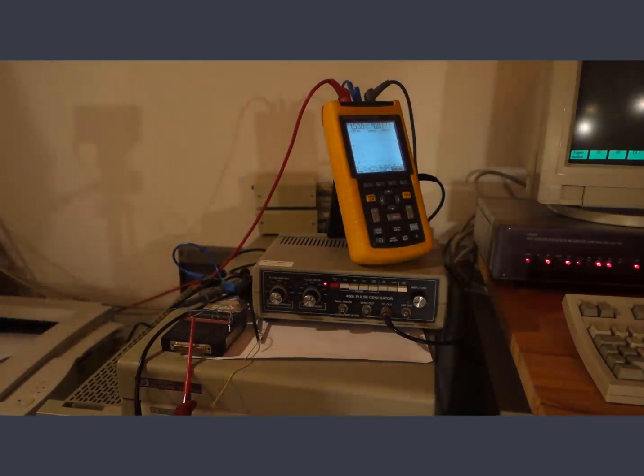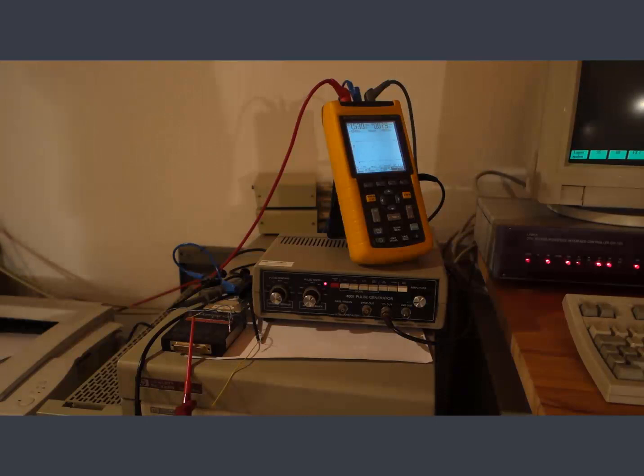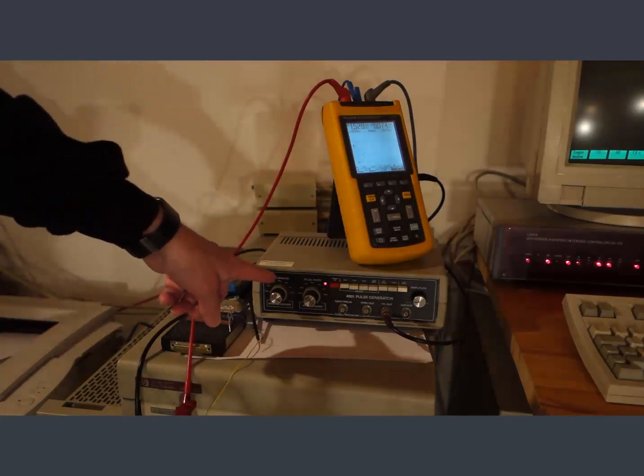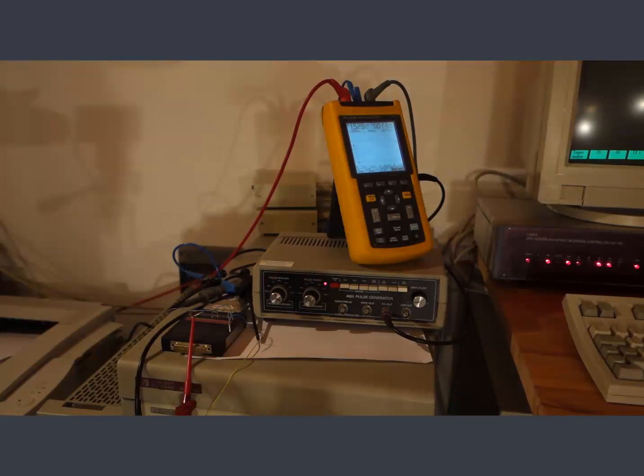Unfortunately, I don't have any IBM PS2 server here. Instead, I have connected the CSI 101 to the parallel card in the HP1000 CPU. And the cable, which normally goes to the parallel port in the PS2, is here connected to a pulse generator, which simulates the PS2 parallel port by generating an acceptance pulse for each byte the PS2 receives. So let us go and look at the terminal.